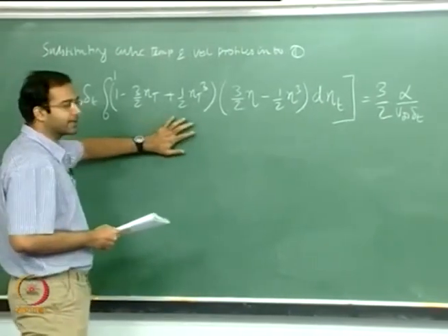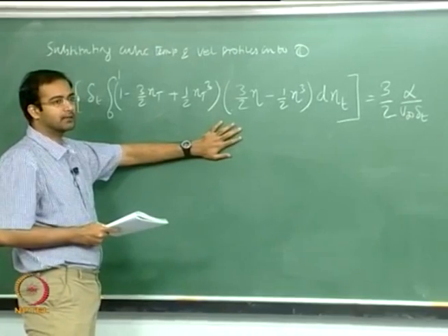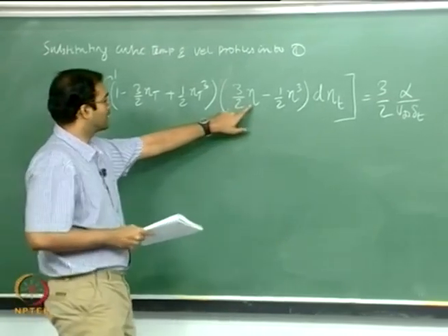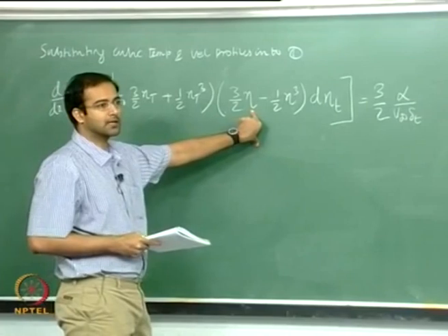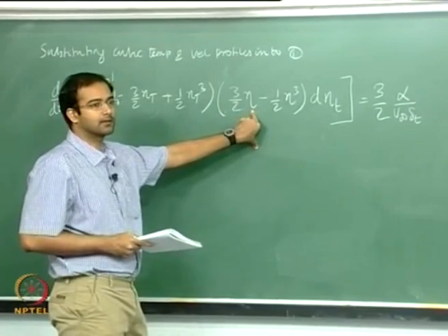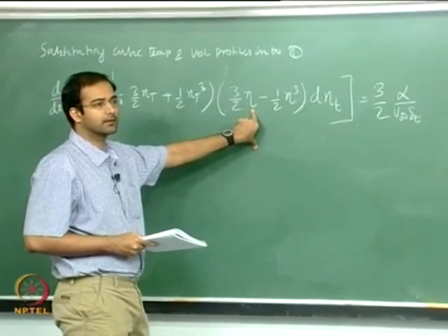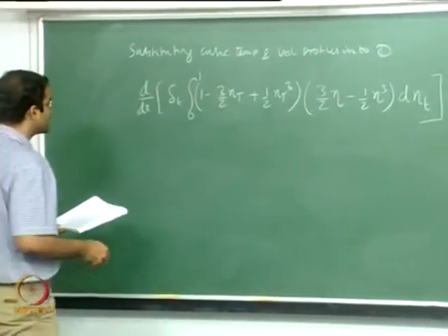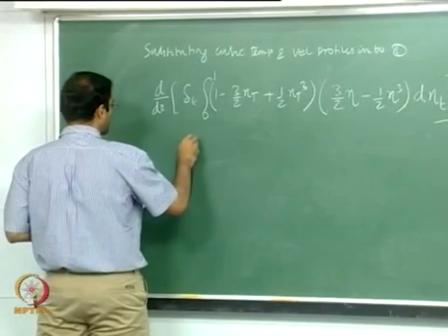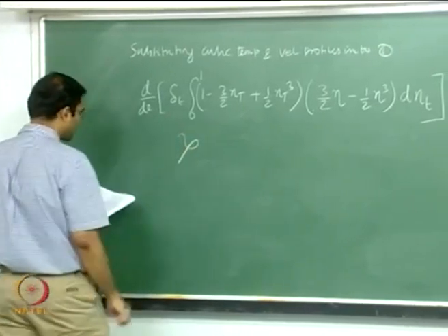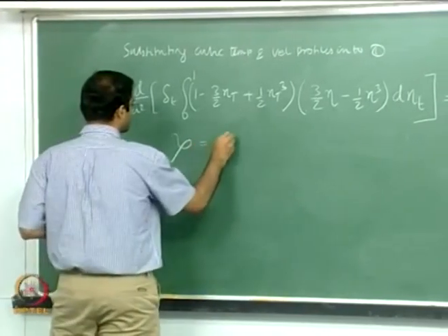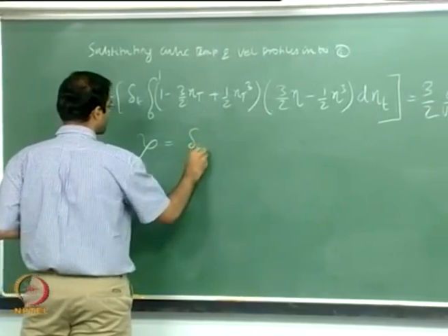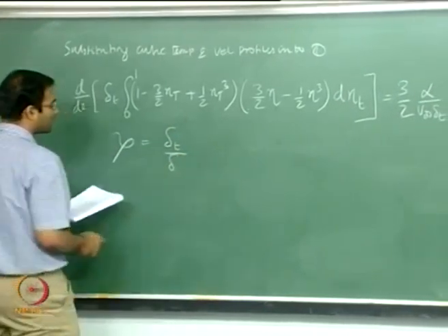Now we have to simply integrate it out. Before we integrate it, we have to write eta in terms of eta t, because eta and eta t are both connected. So we are going to introduce another non-dimensional variable. I will call this zeta, which is nothing but the ratio of the thermal boundary layer thickness to the momentum boundary layer thickness.